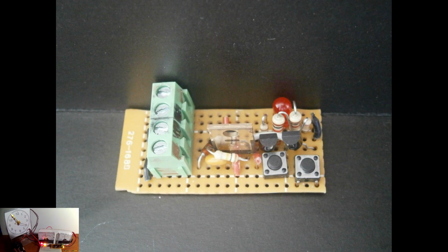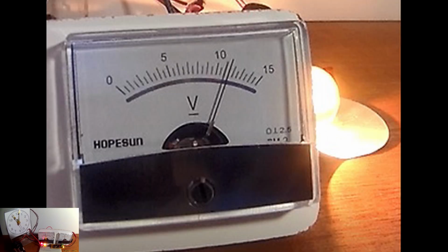The circuit built used MOSFET IRF540 for M1 and MOSFET 2N7000 for M2. Diode D2 was a 12 volts, 1 watt Zener diode, 1N4742A. No R-sense resistor was included in this build, and during the tests, the circuit stayed on for more than 1 hour while driving a 12 volts, 2 amps automotive bulb.